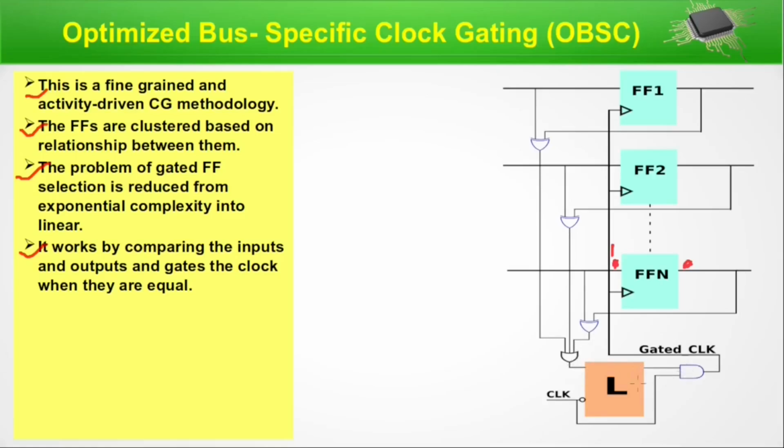So that data will be here, and with the rise of the clock, when that is 1 also, 1 and 1, the clock will be activated here and that 1 will transfer to here. Again, when 1 and 1 both are transferred here, the output of XOR is 0, others are not changing. We are done with this slide.